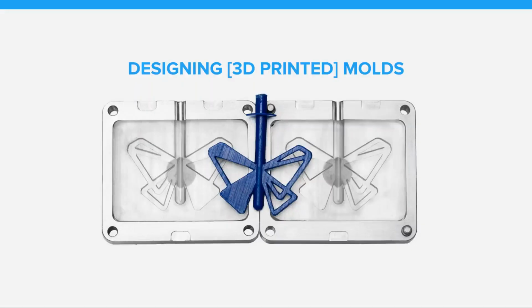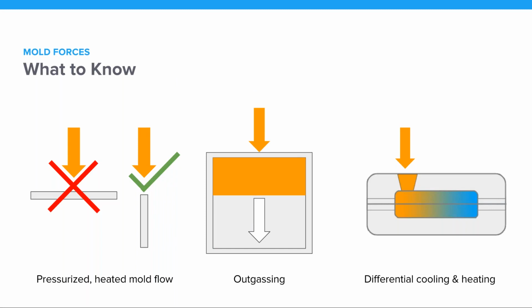So we've talked a lot about molds in general. Let's talk about how to design molds and how to design 3D printed molds in particular. The first thing you have to think about is the mold forces. So we're going to be talking here mostly about injection molding and transfer molding, a little bit with casting, but casting really doesn't have that many forces.